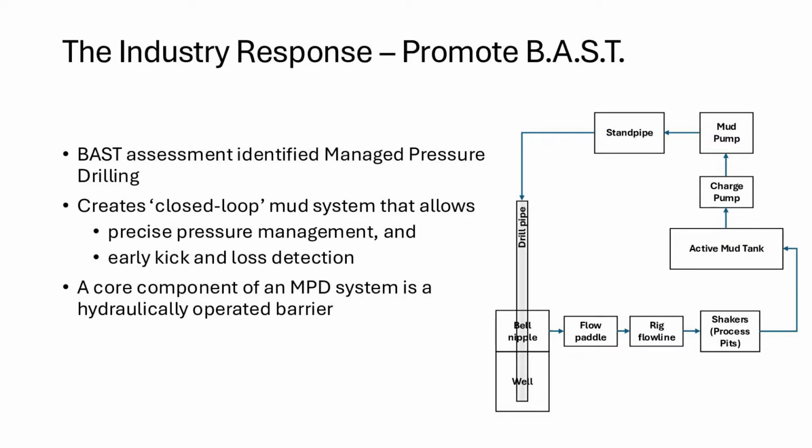The industry response was to promote the use of best available, safest technology. BAST is a test to ensure the most advanced, effective, and safest technology option is chosen by drilling companies and suppliers, all within the constraints of practicability and economics. So the BAST assessment had identified managed pressure drilling as a promising technology. It creates a closed-loop mud system that allows pressure management and early kick and loss detection.